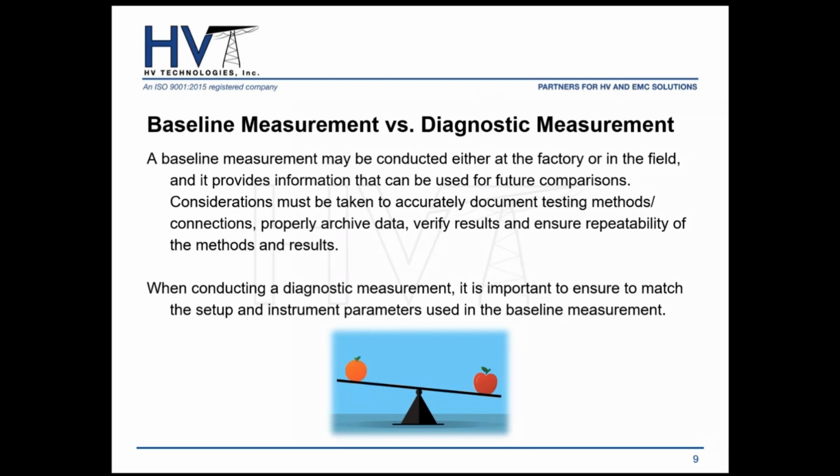So every time you do this type of test, the goal is to have your test setup match as close as possible to the baseline measurement. That way you have a record or a way to compare directly. Once you're conducting a diagnostic measurement after your baseline, it's important that you match the same setup and the same parameters that you used in your baseline measurement, just so you have an accurate comparison.